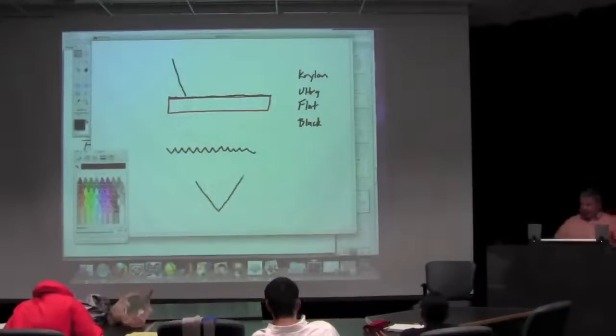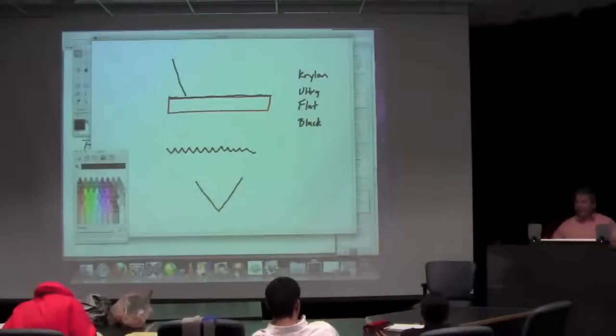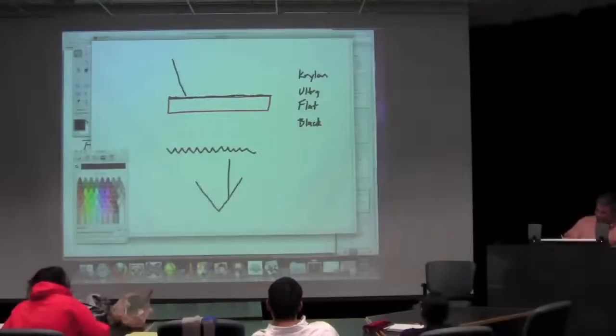All right. Now, if I paint that with a reasonably good black paint, let's say it has an emissivity of 0.96. Okay, so not 0.999, but 0.96. If I have a photon, or a set of photons that come down like this, where's it going to reflect? Well, it's going to reflect here, right? And then in this case, the way I've drawn it, it's going to reflect back out. Right? And that's bad, right? Because a photon coming in left. So that means the reflectance isn't 0.